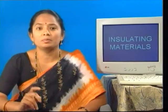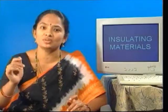The next mechanical property is viscosity. In liquid insulators, viscosity plays an important role. It affects the manufacturing process. For example, in paper insulated cables, the temperature at which the oil penetrates through the paper will depend on its viscosity. Low viscosity liquids are more mobile and hence help in transmission of heat by easy circulation, as in the case of power transformers and switchgears. Liquid insulators should not contain impurities, as they will also affect the viscosity and the performance.